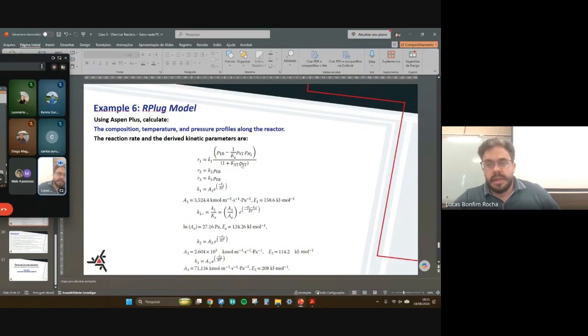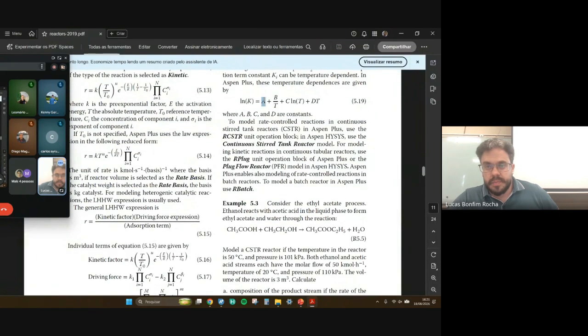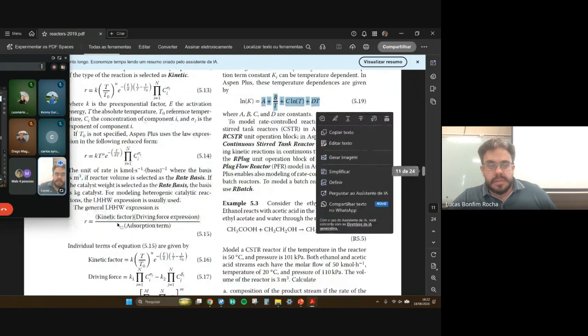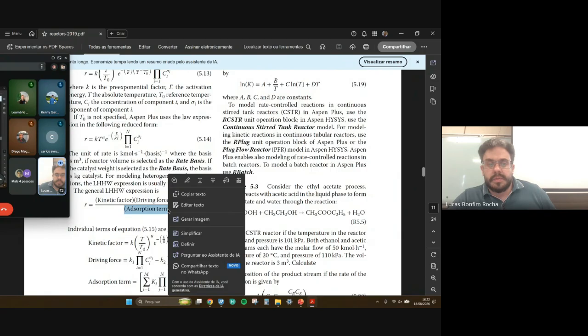For the second term, the exponent for styrene is 1, and for the coefficient KST, we need to specify the value calculated by this expression. So it's necessary to estimate this coefficient using this equation for defining the coefficients in the adsorption term.